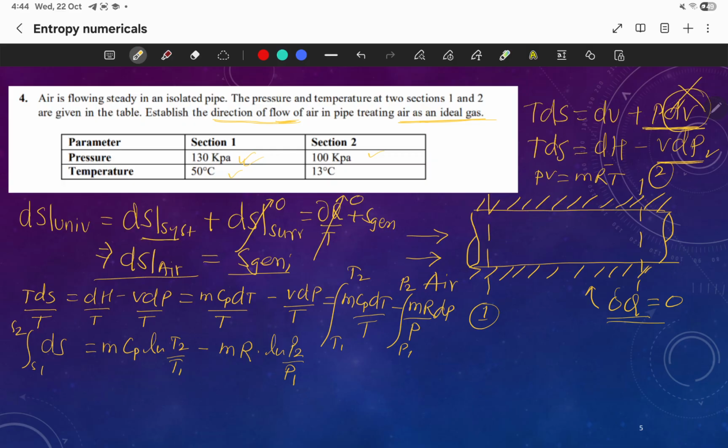okay, so यहाँ पे यार ये चीज़ ध्यान रखना है that for R की value अपन लेते हैं, we take R of air as 0.287 kilojoule per kg Kelvin. ओके, सो here whole thing will be per unit kg, per unit mass, right? सो m की value कितनी हो जाएगी यार, यहाँ पे m की value 1 हो जाएगी. We will take, because here everything will be in per unit mass, so just divide it by mass. We will get what?